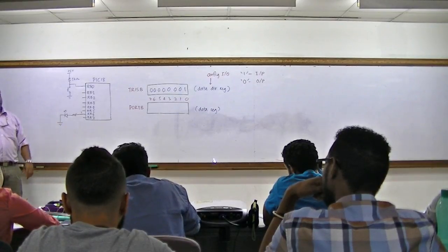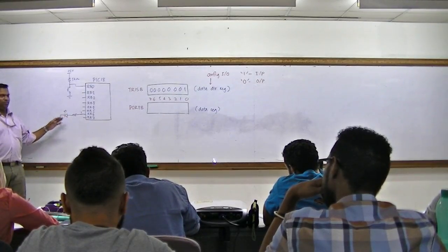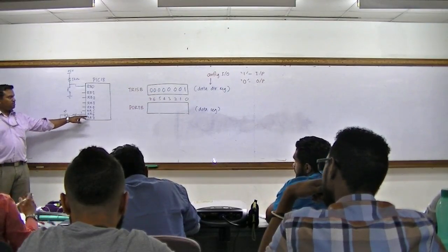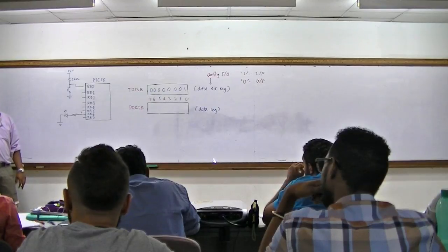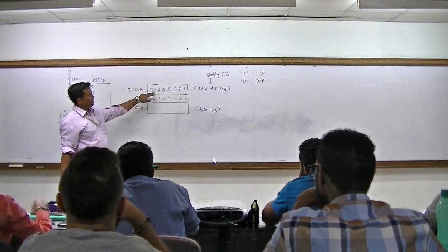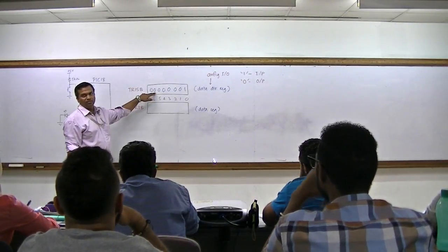Okay, that's a different story. Now we have made this configuration at port B pin number 6. So which means this pin number 6 is supposed to be output, right? Because here we already configured it to become output, so it's okay. Fine, so it will work.